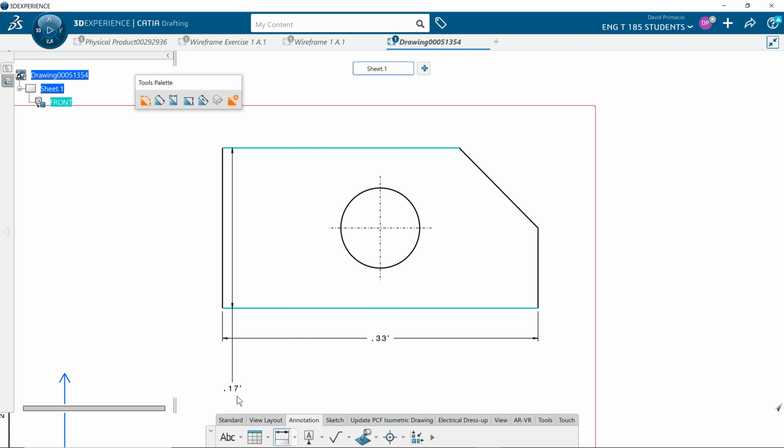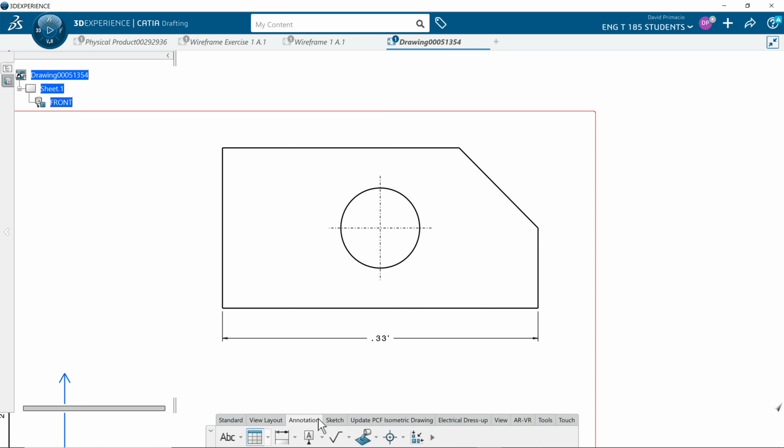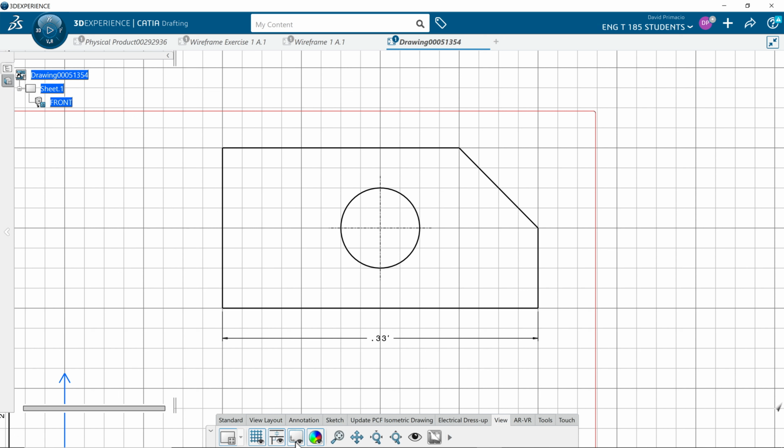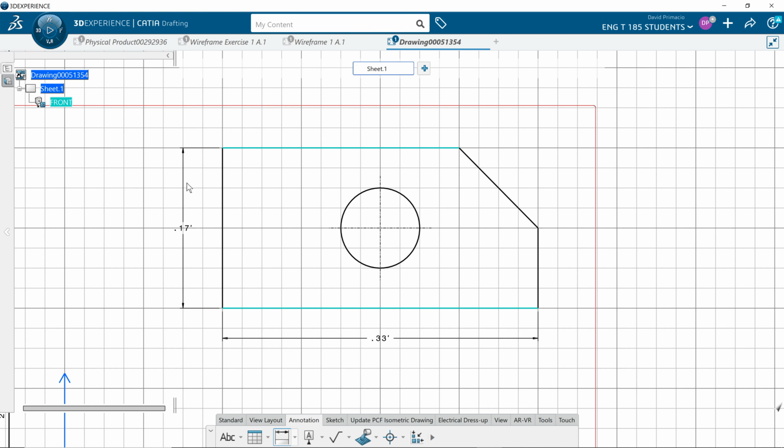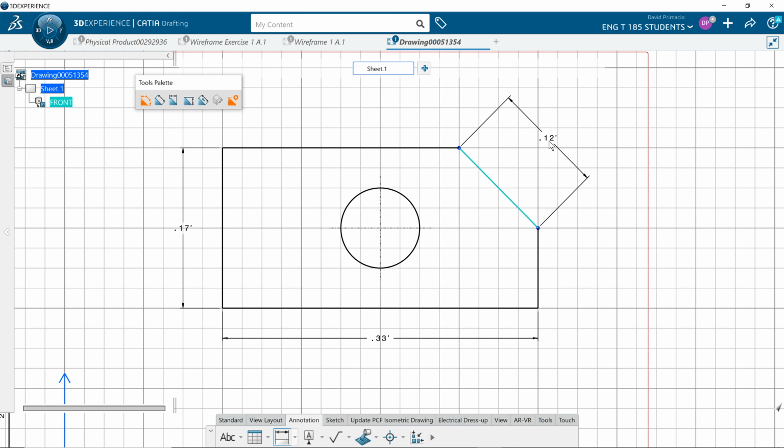Now what I do is I normally have the grid on already. So when I create my dimensions, I can set it to the grid accordingly. Again, under offset, I'm going to select the endpoint and another endpoint, and you get an aligned dimension.